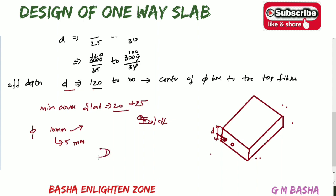So what is the overall depth? Overall depth will be D plus diabar by 2 plus remaining cover. The cover for slab will be 20 mm, and the diameter we are generally adopting is 10 mm, so half means 5, plus this effective depth, which will be 120.